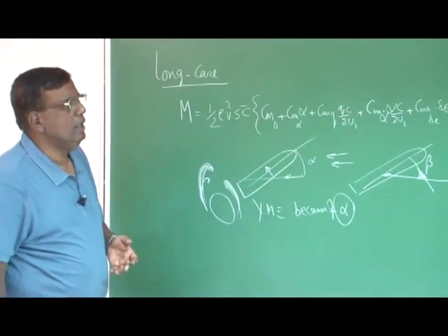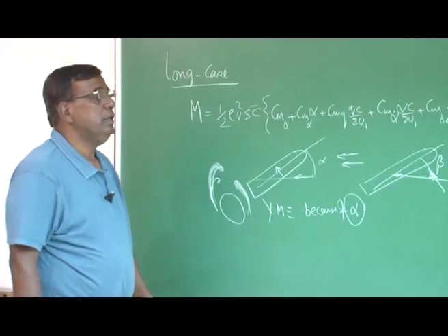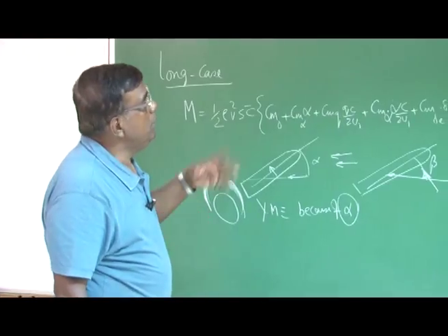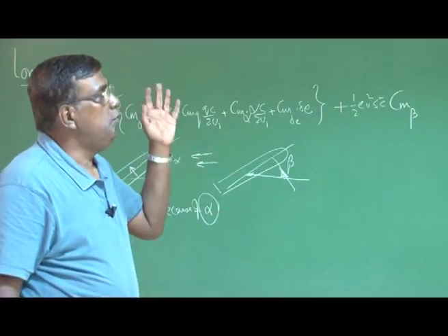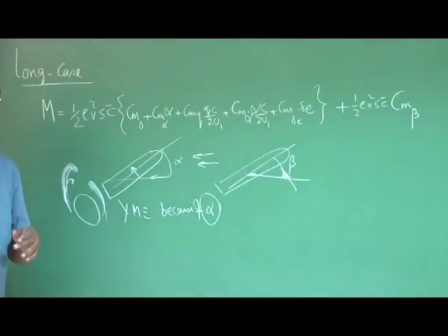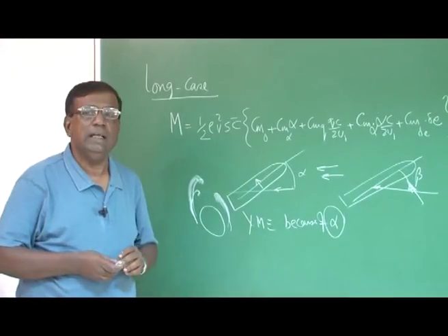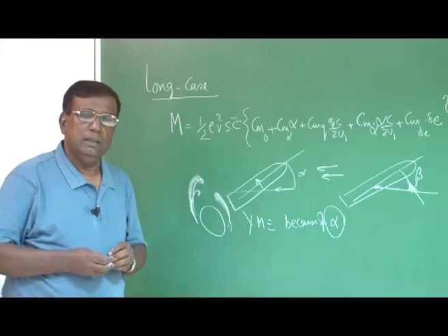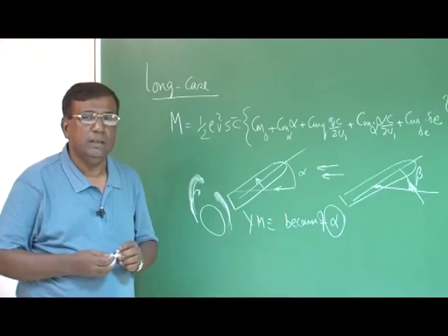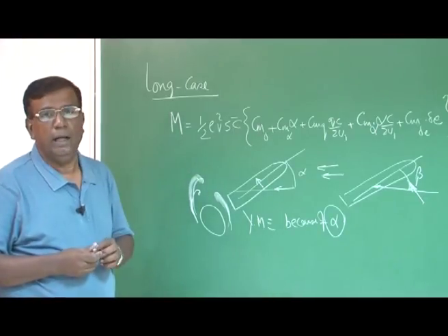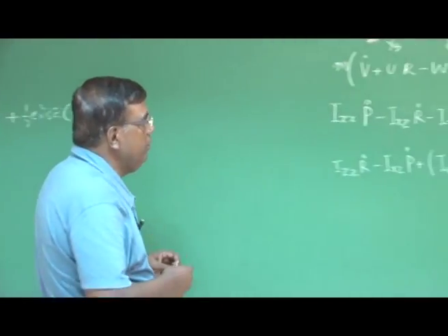Similarly, there will be terms which are dependent on the rates, on the history of how the flow has built up, because of high oscillations. So the whole of this aerodynamic model becomes highly nonlinear. However, so far whatever we have developed, we have assumed things are linear, right? So that becomes a challenge for analyzing dynamic stability by using this method. Yes, if you can linearize this judiciously, then this can be easily applied. But this is an area which we need to understand and keep at the back of your mind.